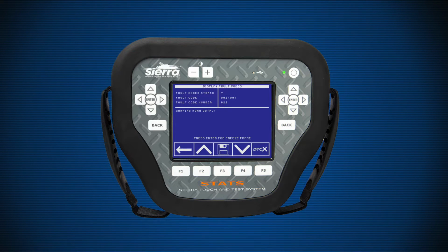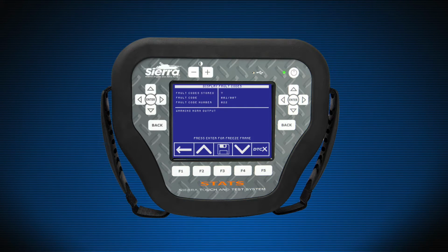This function will safely clear all fault codes in the ECM memory. Some engines save multiple fault code memories, such as active, occurred, and historical. Active and occurred fault codes need to be cleared individually. Historical codes are not resettable.